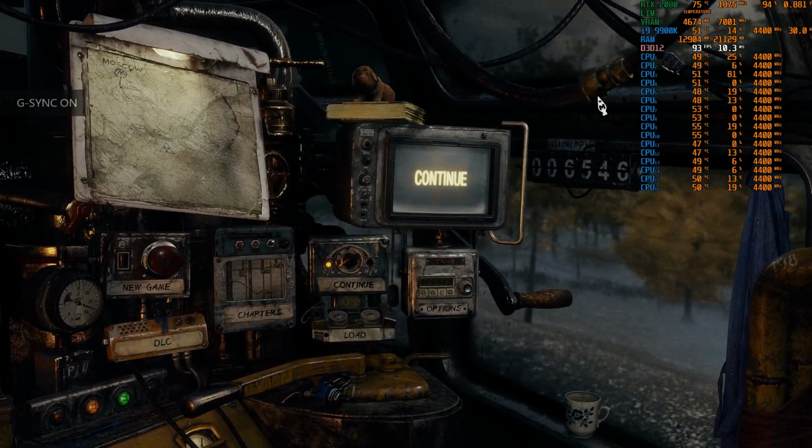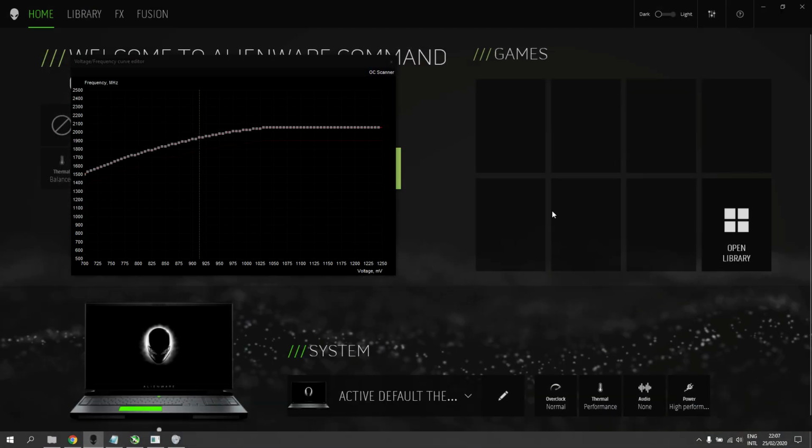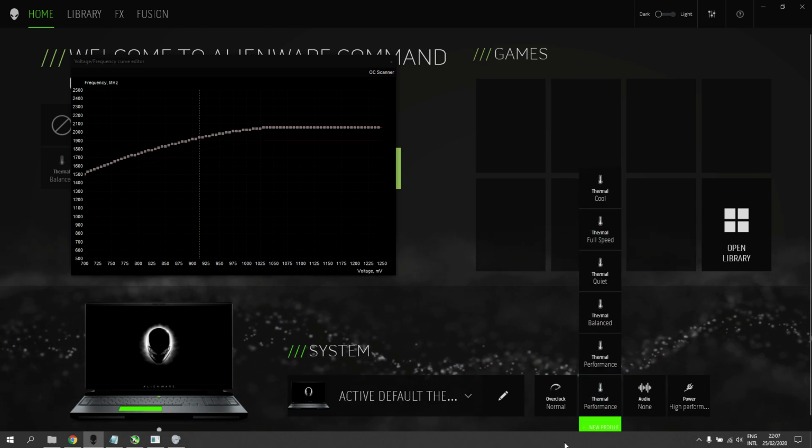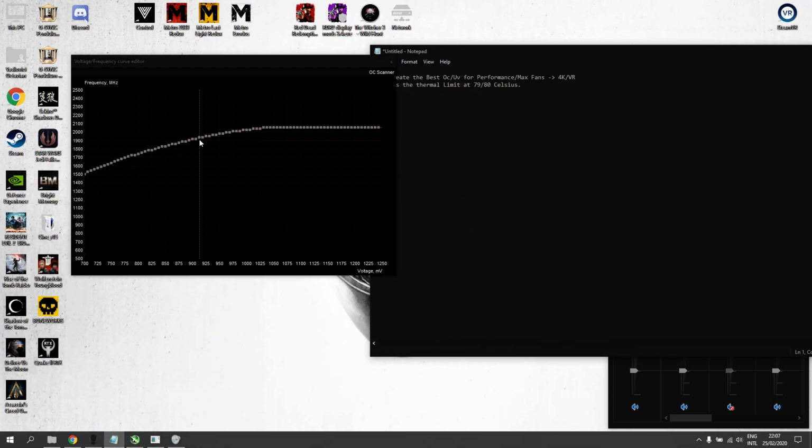So yes, which means that first thing I'm going to do is actually no, I'm going to keep it on performance. Yeah. So fine. Apparently our profile doesn't allow us to go higher than this. But even at this voltage we are hitting the power limit. So I guess this is the maximum we can push this card. If we try to increase the voltage, we need to increase the power draw, which is controlled by the vBIOS. Obviously, you can flash an older vBIOS, but I wouldn't recommend it. The 1.003, which is a 200 watts cap, will actually allow you 20 watts more, but yeah, you'll not get a lot more performance for the heat it generates, but you can try it.